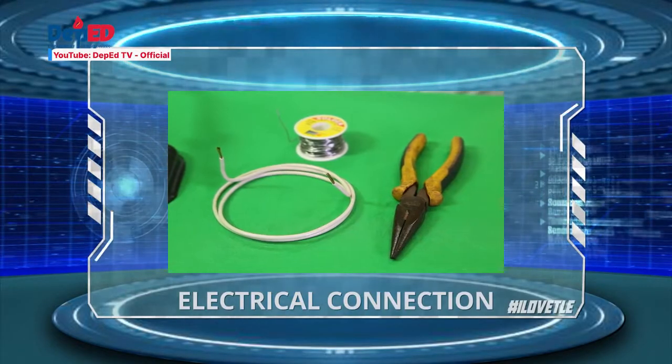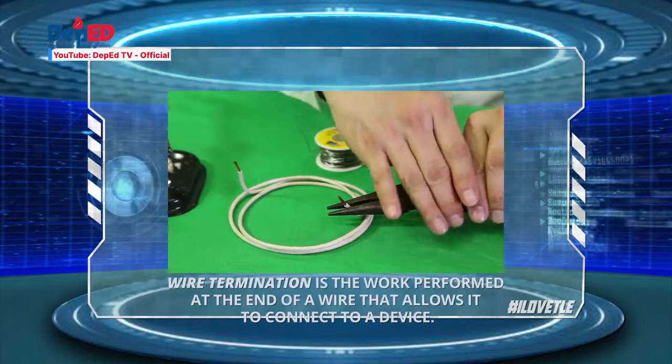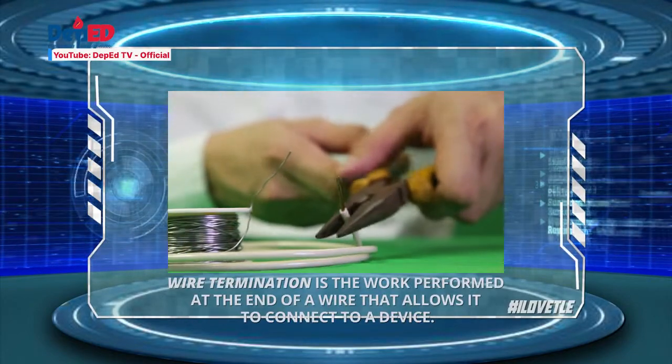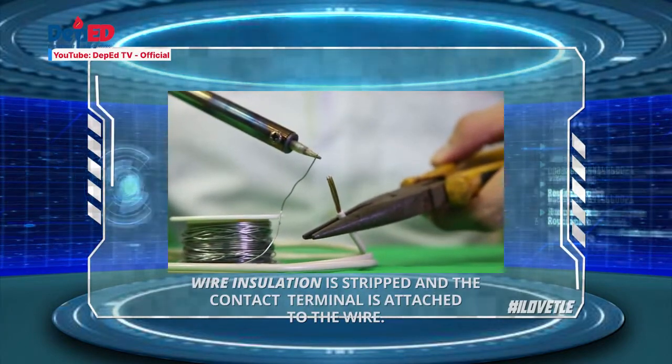In electronics, there is a process called electrical termination. A wire termination is the work performed at the end of a wire that allows it to connect to a device. The wire insulation is stripped and the contact terminal is attached to the wire.